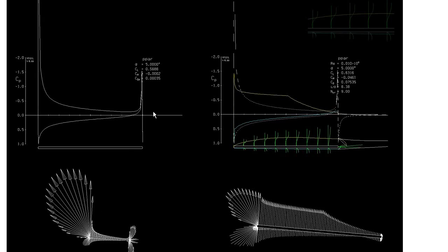And to see the pressure distribution as a vector graph, we have those two nice images. So again, the arrows are basically blowing up. The scale of this figure is different because we have a small size of this plate. And this graph, if you put it there, it's going to be like this. So it's definitely different, and the solution is very different as well. And the number for the lift coefficient is different, and so on. So the viscous mode is the way to go.